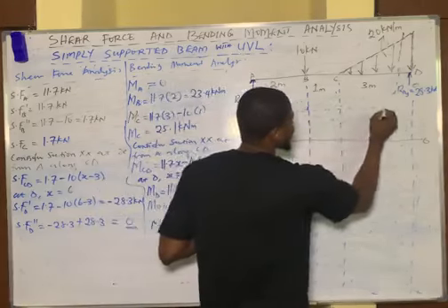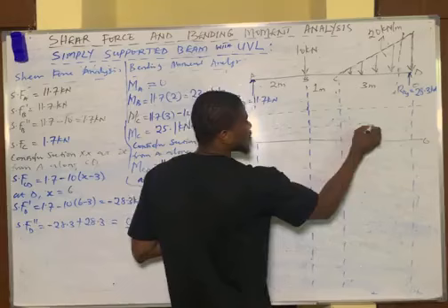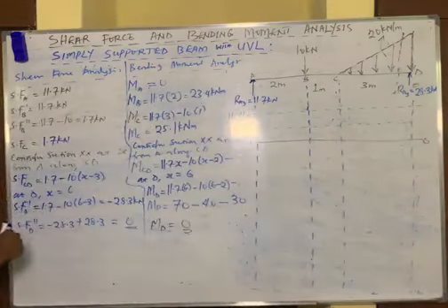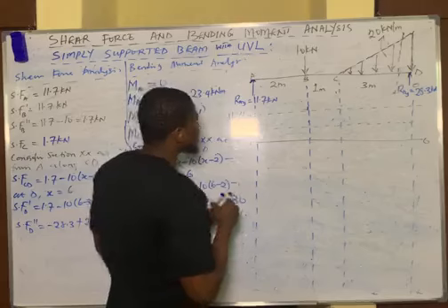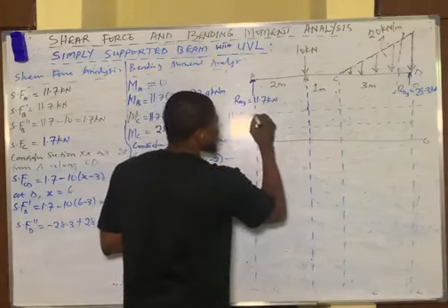So you trace out the points. Okay, let's now plot our shear force diagram. Shear force at A is 11.7. This is line A, not forgetting. 11.7 is here. This is where it connects. So you mark an asterisk for shear force at A.